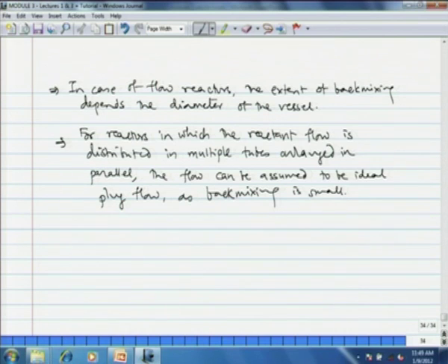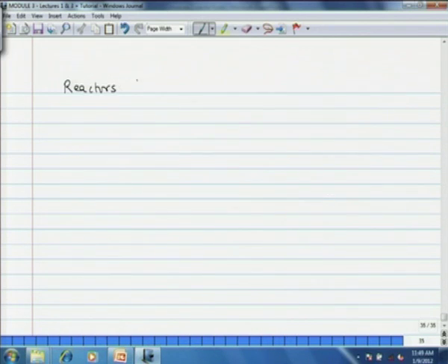Now the topic of fluid solid reactors. These are essentially the catalytic reactors. Use of catalysts requires special reactor design to account for the mass and energy transport issues. Here the mass transfer limitations are more pronounced. There are various designs available based on the relative motion of the reactant. The three basic types of reactors are, first, a single fixed bed reactor. I will show you a basic sketch of these reactor types.